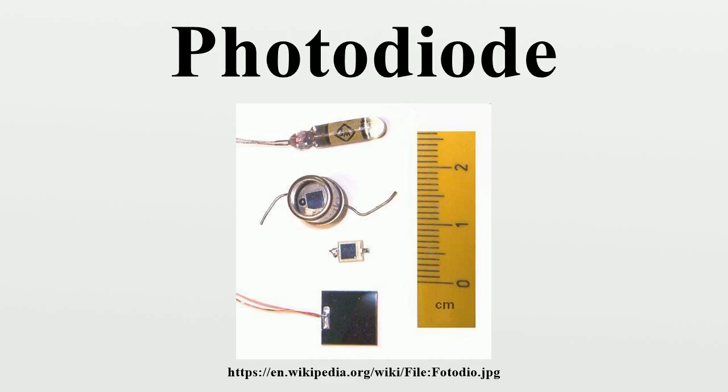Photoconductive mode. In this mode the diode is often reverse biased. This reduces the response time because the additional reverse bias increases the width of the depletion layer, which decreases the junction's capacitance. The reverse bias also increases the dark current without much change in the photocurrent. For a given spectral distribution, the photocurrent is linearly proportional to the illuminance. Although this mode is faster, the photoconductive mode tends to exhibit more electronic noise.